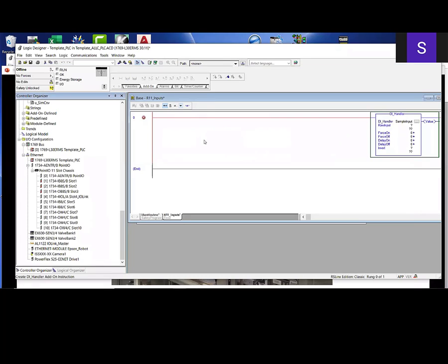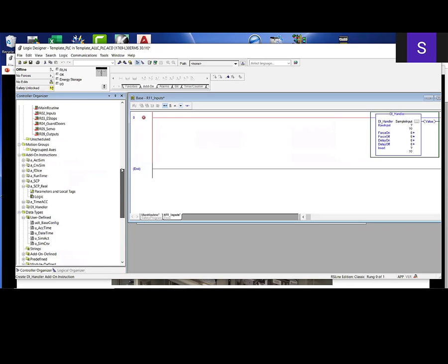So if I go up here, again, there is a safety PLC itself. There is a point IO module, 3 of which modules are safety modules. So this is a safety input module, safety input module, safety output module. What those are is those are dual channel modules for things like e-stops. So when I go to my program, you will see that all the logic for the e-stops will be right here. So dual channel e-stops, dual channel guard doors, dual channel relays. This is a category 3 safety machine. So it's got a lot of safety stuff on it.